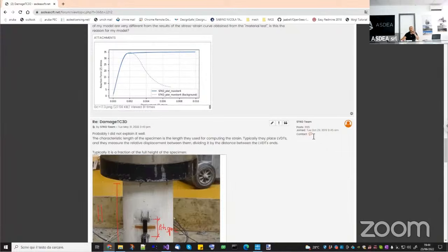I will not do a shear wall with a single beam element, because it's not convenient, in the sense that when you create a beam with a fiber section, it can only represent bending problems. Then if you want, you can aggregate shear with the shear aggregator, but the shear will be completely uncoupled from the bending, at least at the constitutive model level. So it is not convenient to model a shear wall with a single fiber beam element. But yes, I will show fiber-based shell elements, so the layered shell elements, solid elements, and the multiple vertical line elements.